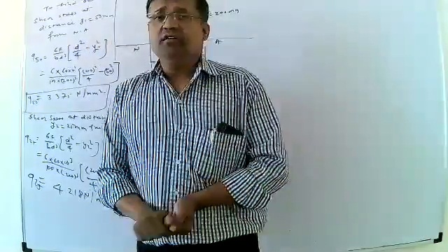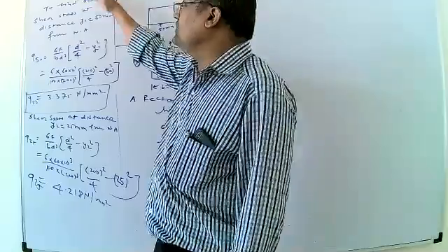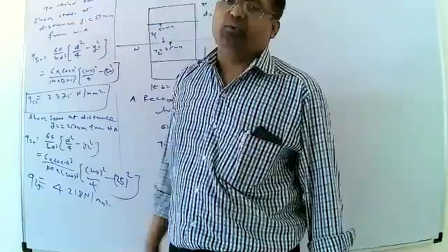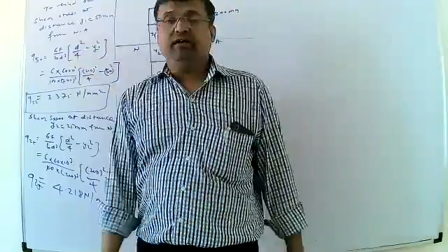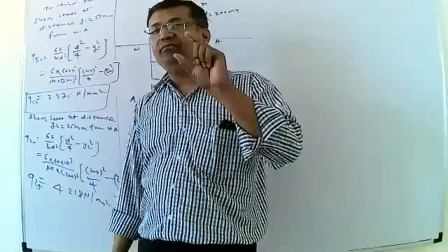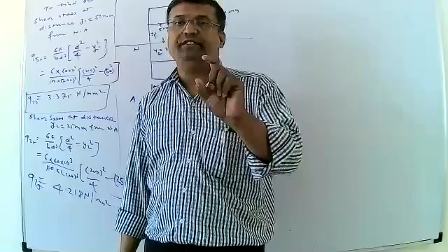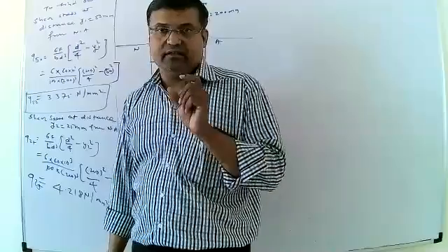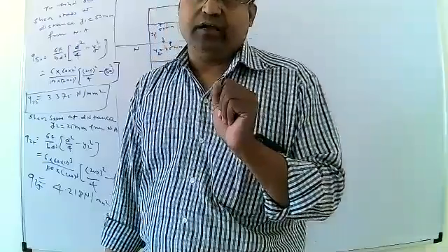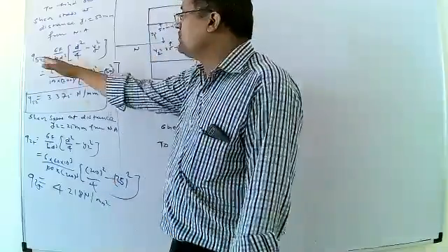Then first we find the shear stress at a distance y1, that is 50 mm from the neutral layer. The 50 mm distance is always considered above the neutral axis. The formula will be the same.